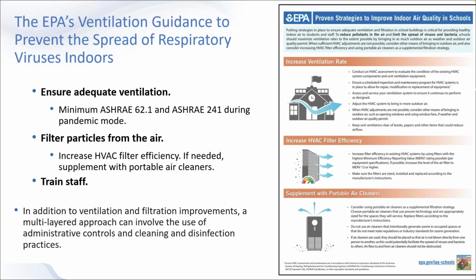In situations where it is difficult or not practical to meet minimum standards by bringing in additional outdoor air, evaluate the use of portable air cleaners and upgrades to the HVAC filters, such as MERV 13 if possible, and potentially supplement with portable air cleaners.